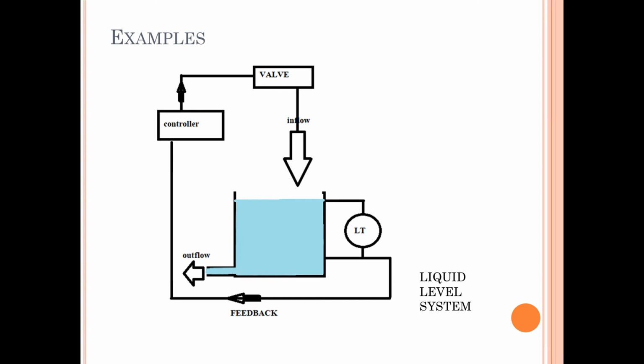And different types of sensors can be used. Those are the tachometers, accelerometers, LVDT, that is linear variable differential transformer, the thermocouples, strain gauge, etc. Generally, these sensors are used to measure the control variable of the system. Now, the system has input variables which can be manipulated to modify the control variable, and those variables are known as the manipulated variable.